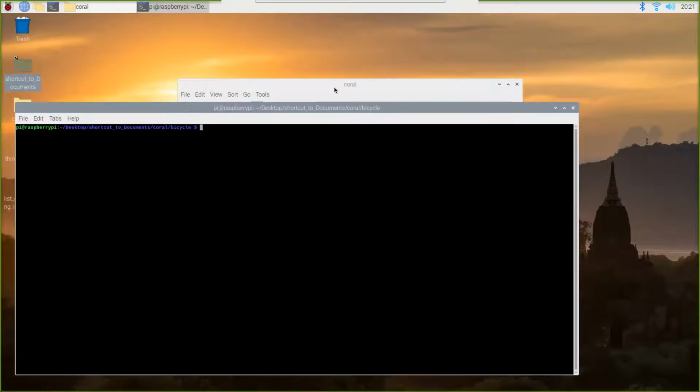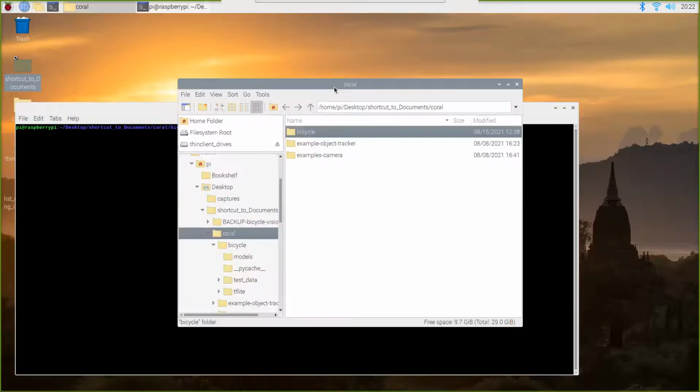Right now, we can change it, but whenever you see that red outline in the video, it turns on the buzzer, and when the red outline goes away, it turns off the buzzer. Okay. I have a newer version of it, which I'm not going to show right now, where it adds a little bit of hysteresis. If the buzzer turns on, it makes sure it stays on a minimum of 2 seconds, because sometimes you'll get a little blip where it'll detect the car, and then it won't detect it, and then it will detect it. So it smooths some of that out to make a better experience.